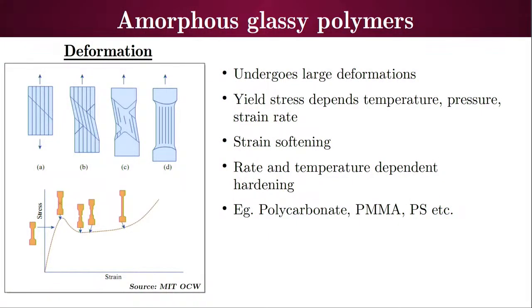What would that look like in your framework? That is probably the anisotropy of the polymer. If it is isotropic, the property should be the same in all directions. The behavior should be the same in all directions. For example, if I take a polycarbonate sheet and cut two specimens in two perpendicular directions, I should get a similar kind of behavior. Yes, but that's because it's been produced in such a way that it doesn't have any preferred direction. But plastic bags are very anisotropic.